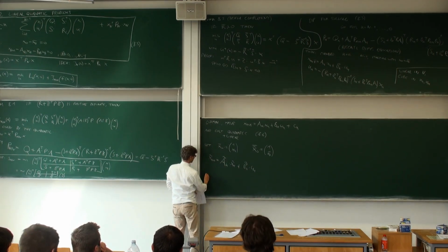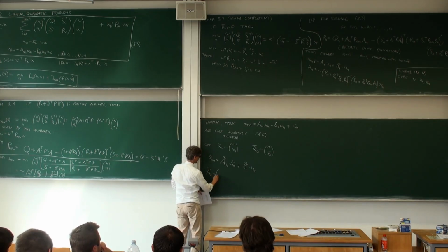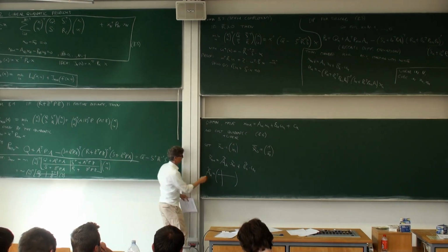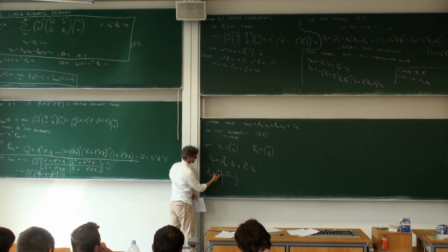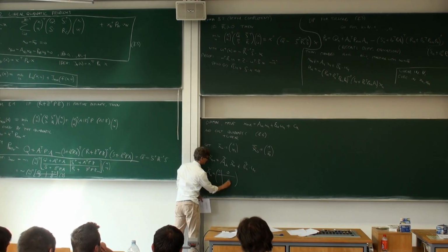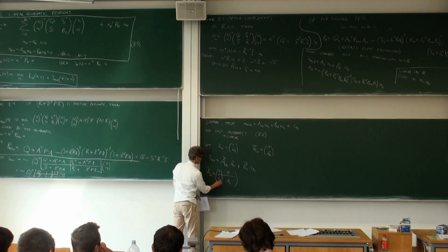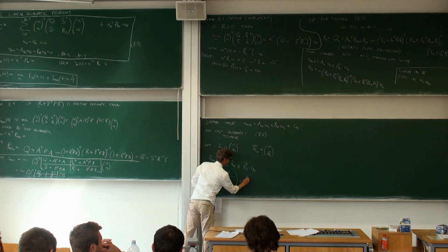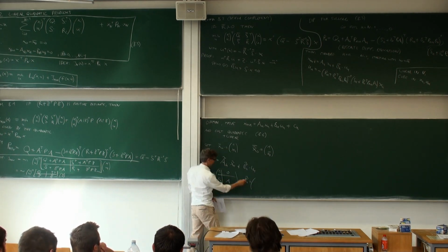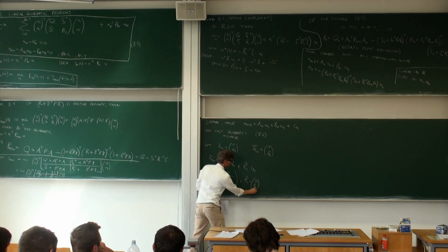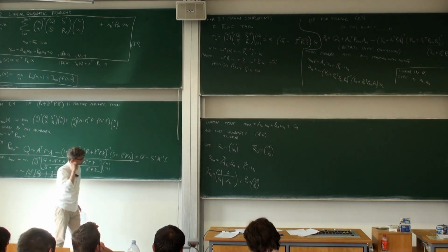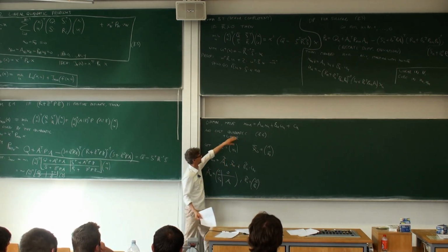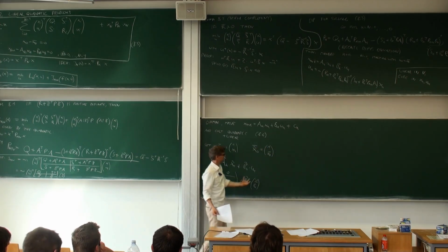And how do I define these matrices? A tilde k is the old matrix, but it introduces an extra dynamics for my dummy state, which will just be propagated. So it will just remain at 1. Here's my matrix A_k, and here's the c_k part, so this affine part. And the matrix B tilde k is just given by no influence for the first part and B_k for the second. So with these system dynamics, I'm back at a homogeneous system, without an affine term, without this constant term.